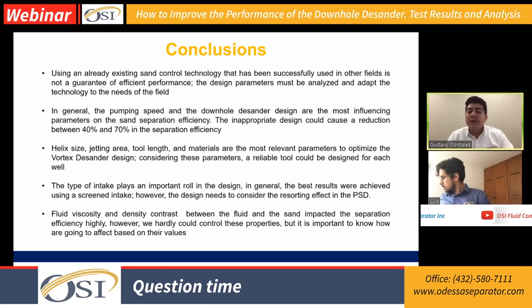In a new well, when I don't have enough bottom pressure and I need to put my ESP to start dealing with the majority of that frac sand, I can fill my tailpipe super fast, but having the two stages is going to give you a better handling method to start lifting the particles and cause less abrasion and erosion damage on the sleeve itself. So be sure the screen is not for all the wells.